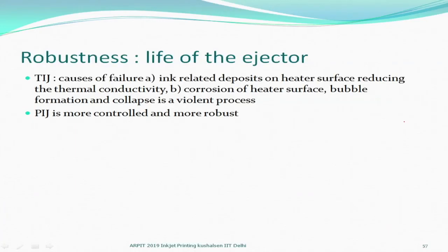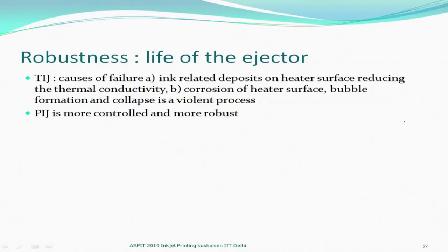In general, people believe that the TIJ, which is the thermal inkjet system, can have deposits on the heater surfaces, therefore the conductivity may be changed, and so how much displacement and temperature rise will be there may change with time. Corrosion of the heater surface can also take place, and the bubble formation and collapse is basically a very violent process.